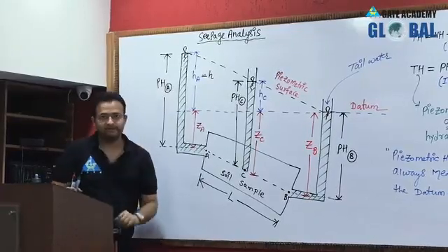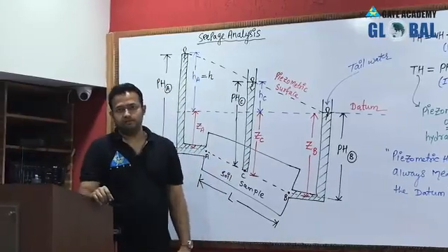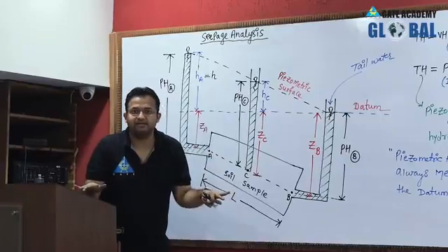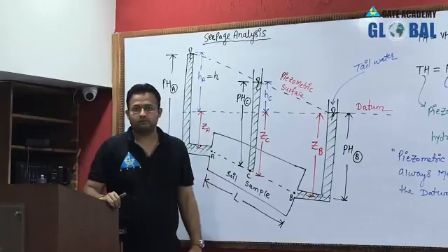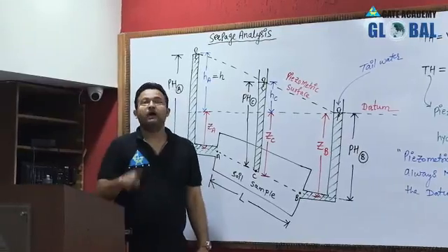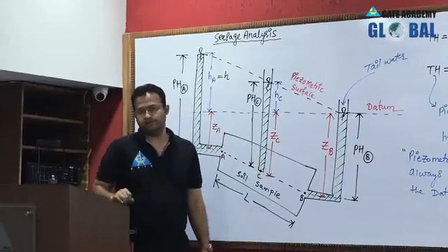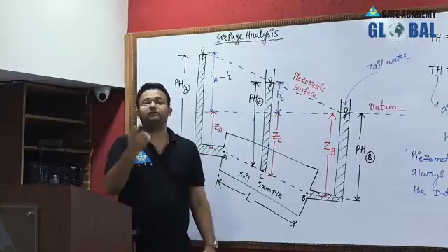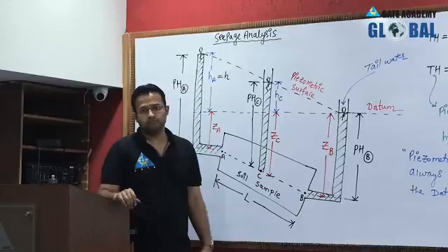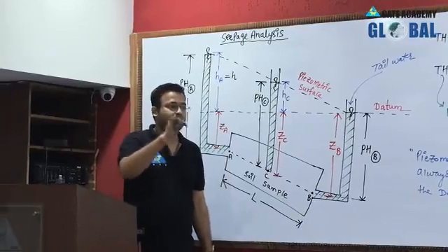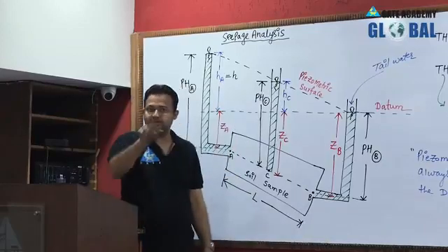This is not a static pressure, it's a flow. Only when the water is flowing will this pressure act. If water is not flowing, it is in the hydrostatic condition, then the seepage pressure is 0. This will not occur, only pore pressure occurs. Under the static condition, the pressure the water exerts is called pore water pressure. But when water is under the dynamic condition, meaning the water is flowing, then it will exert a pressure on the soil solids which is called seepage pressure. So there is a difference between seepage pressure and pore pressure.